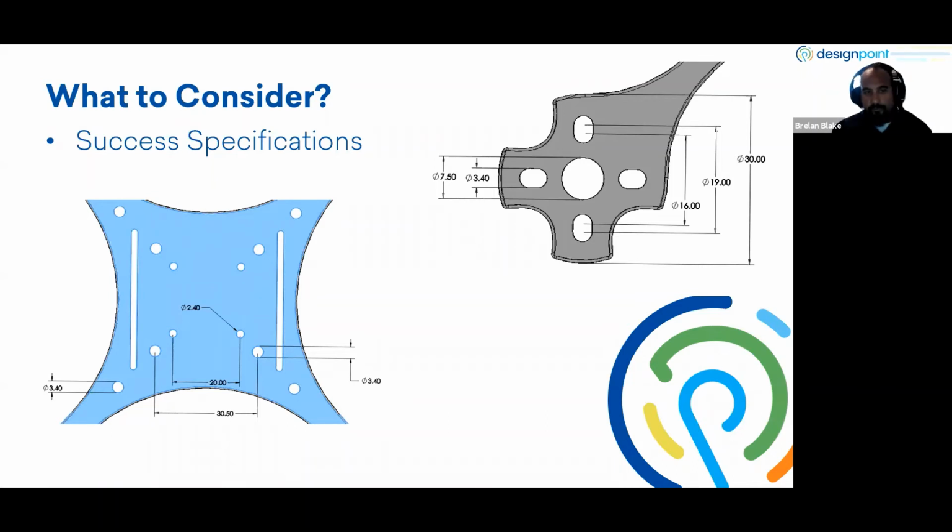Those are for Velcro straps to strap the battery down to the bottom of the frame. We had those slots a little bit further out to the edge, and we had to have a minimum of 2.8 millimeters from the edge, and we pushed that in, and we actually went with over 3 millimeters for that continuous fiber to run the whole way around the frame, which we'll explain just a little bit later.